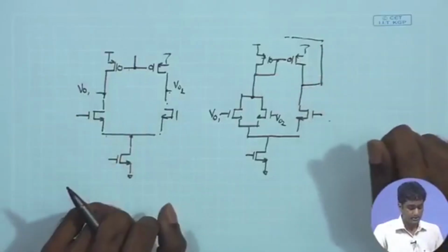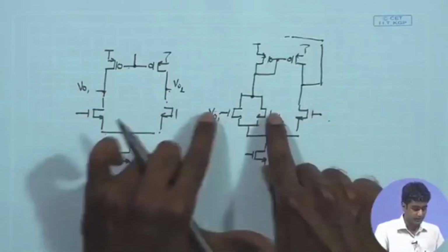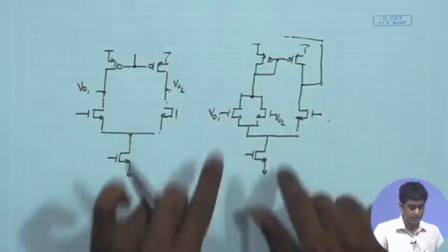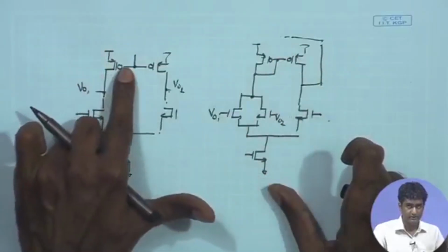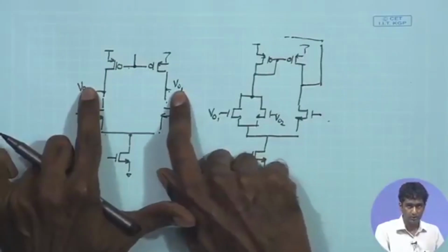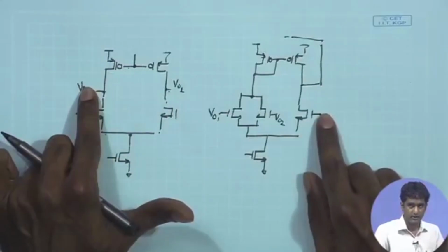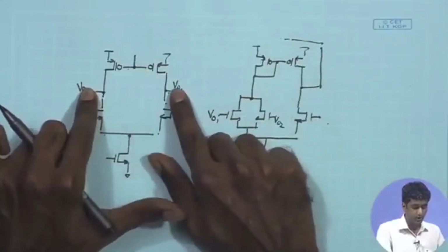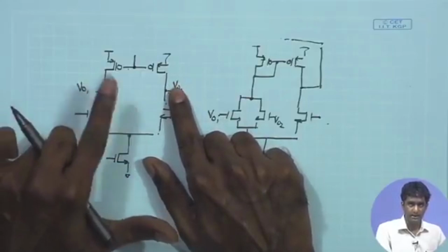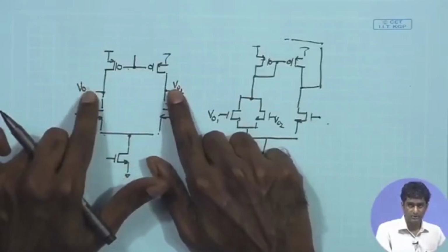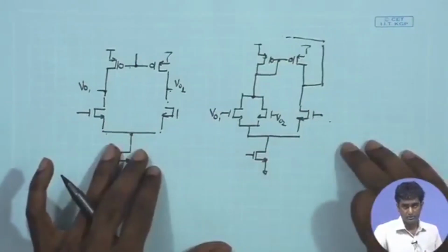The other option is that, as we have discussed in the theory session, we can open the loop over here. So, we can disconnect the input of the error amplifier from the two outputs, and then keep the connection between the output of the error amplifier and the PMOS as it is, and then observe the final output coming over here. Under that condition, we will be applying an AC signal over here, and of course, since it is going to be a common mode operation, both the outputs will be changing in the same fashion, and therefore, that behaves as my final output, that is the A beta factor. So, observing this signal is equivalent to observing the A beta times the input signal. So, these are the two ways in which we can do it.